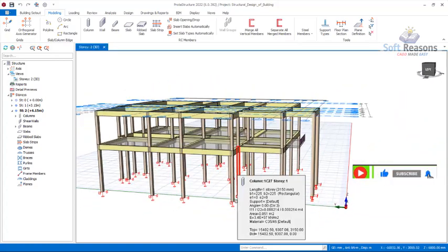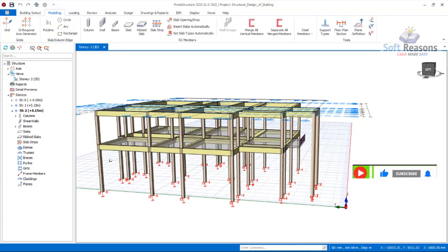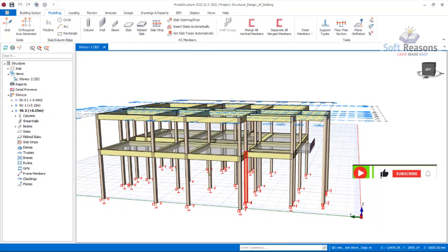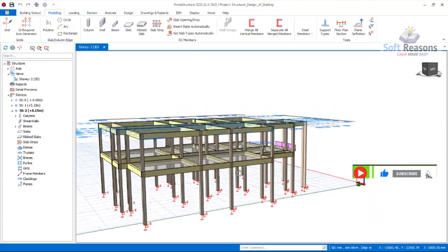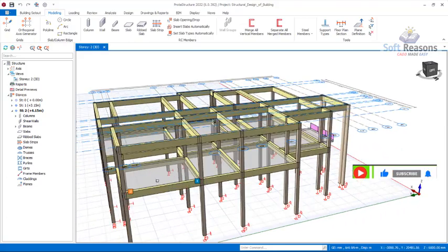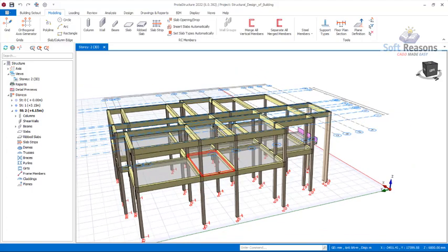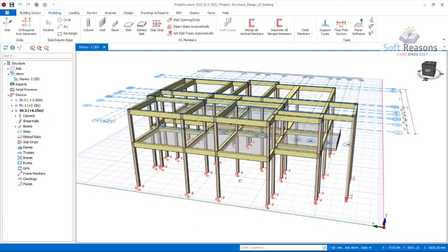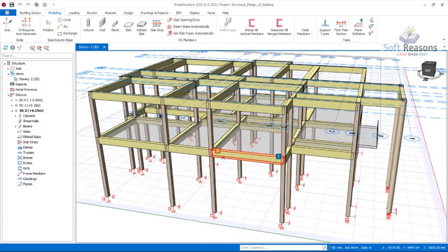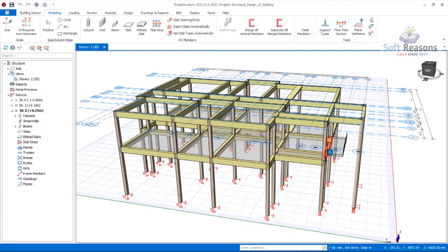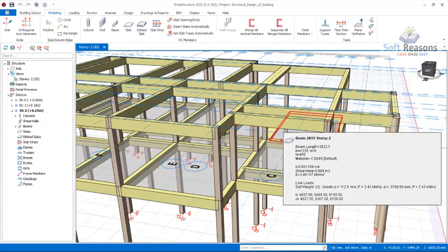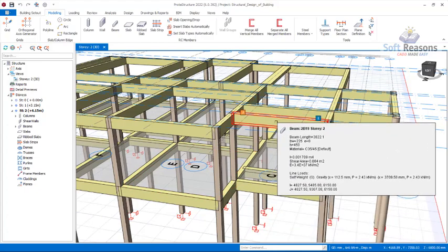At this point, we will proceed to load the structure in terms of the wall loadings. Alright, so we load the structure. For us to load the structure successfully, you just have to navigate to story 1. But before then, you will notice we are having the depth of the roof beam to be 450. So roof beam is not supposed to assume depth of 450.